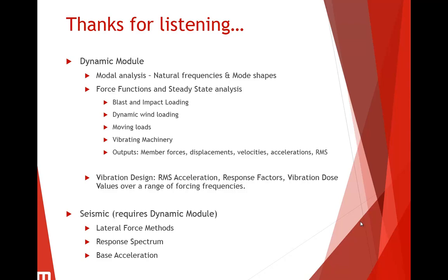We can do either of the analyses. We can do the analyses with the SCI, P354, or the Concrete Society, and do transient or steady state analysis. And we can use the Fourier series from either of these approaches, or define our own Fourier series. And finally, we can also choose to use just a range of the modes or a selection of mode shapes. This really could reduce the analysis time, especially for the separate areas analysis here, where we have our vibration occurring in a different area to our response factor, which can sometimes take quite a while.